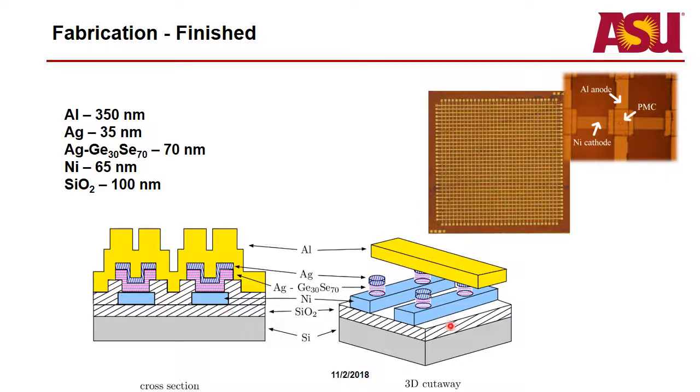And so here, this bottom figure shows a finished cross-section of a crossbar array. So the one step I didn't show was the lift-off of this aluminum bar. But essentially, the finished device is this crossbar here, where you have an underlying nickel bar. You have the device here, and you can see that via where the actual active device area is, and then you have the top aluminum bar that goes across the device area and also helps to protect it in addition to giving it an electrical connection.